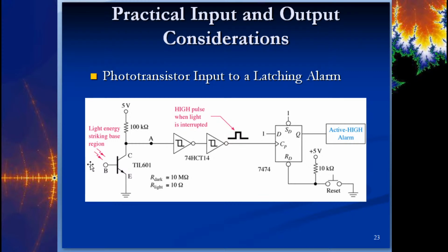So instead of just having a voltage or a current on the base that's high enough to drive it, it's connected to a photocell. If there is enough light that can be converted into an electrical signal, it will turn this on. So essentially it's light dependent to turn the transistor on and create the short, and then you can sink down to ground. Okay? So that signal is either going to be high or low.